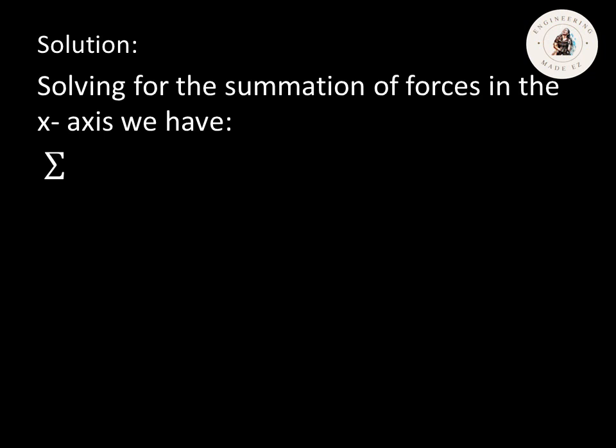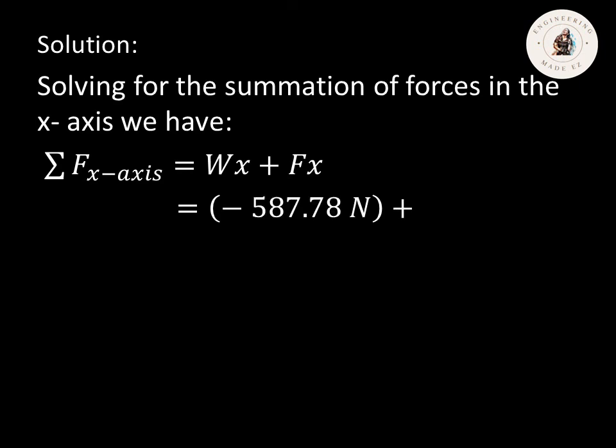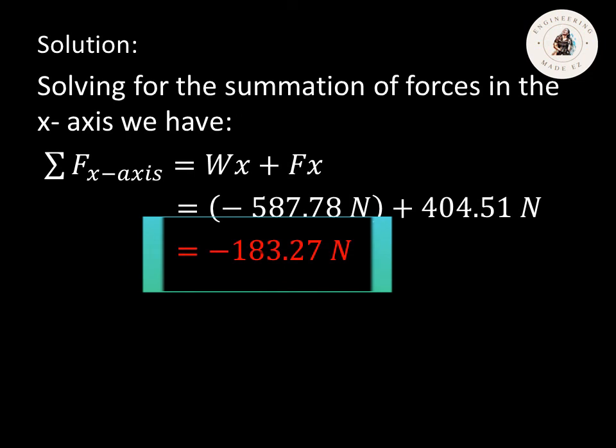Solving for the summation of forces in the x-axis, we have Wx plus Fx. Based on our calculation, Wx is equivalent to negative 587.78 Newton and Fx is equivalent to 404.51 Newton. Adding them, we have an answer to be negative 183.27 Newton.